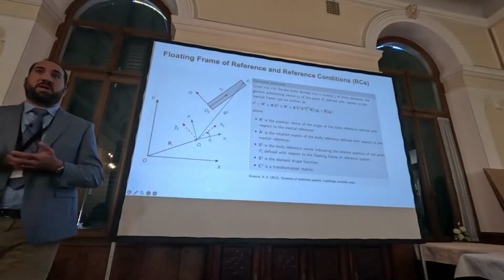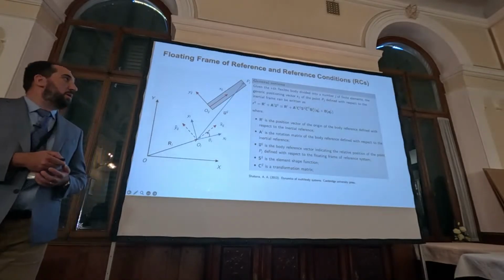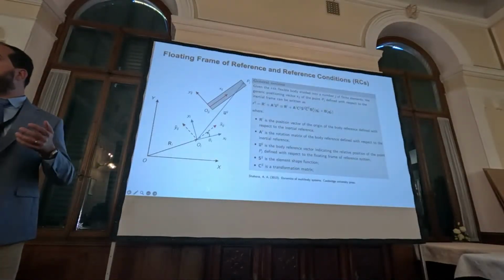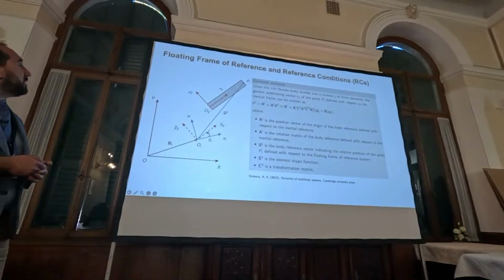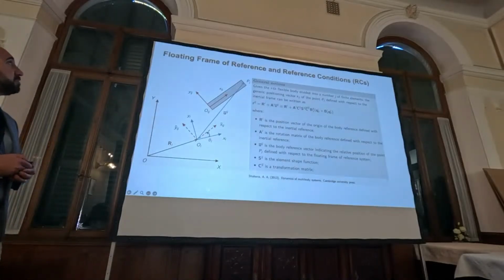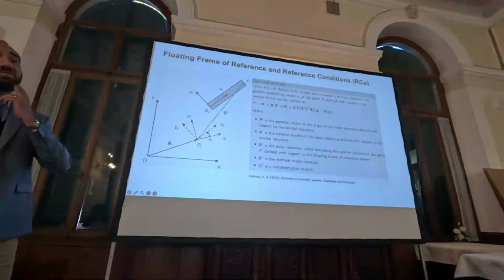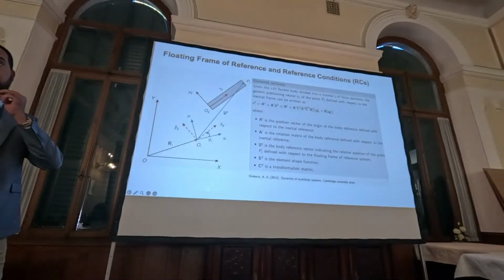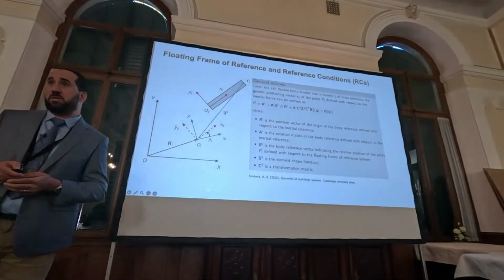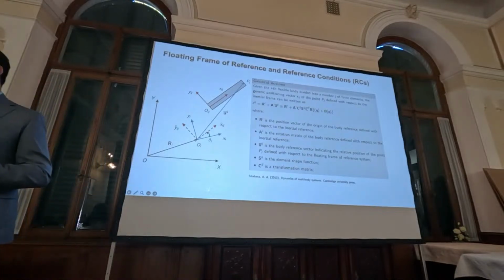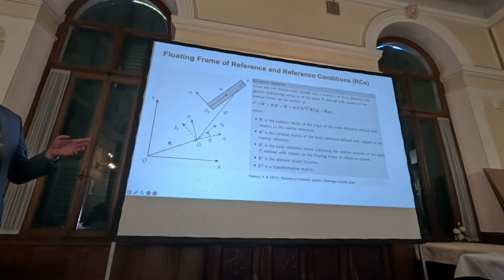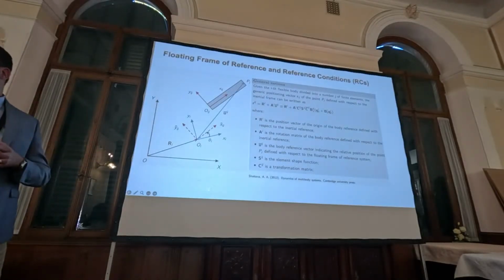After we obtain the contact forces, we insert these generalized contributions inside our method. In this case, we use the floating frame of reference formulation. The floating frame of reference formulation is largely used in multi-body dynamics, but also in common software like Adams from MSC. It decomposes the motion into gross motion and local deformation.